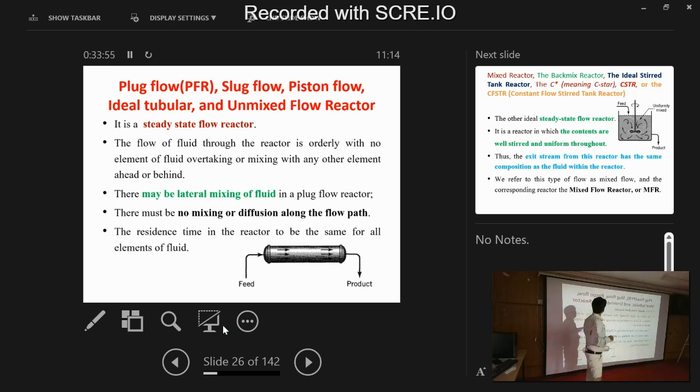And now, why is it called plug flow? There will not be any overtaking or mixing with any other element. What do you mean by overtaking? For example, I have sent some fluid from the first left end. If one fluid particle is here, it will always go in this direction only. It will not come back. When I feed it here, it goes in the same direction with whatever velocity I kept. That means it will not react with the back particle.